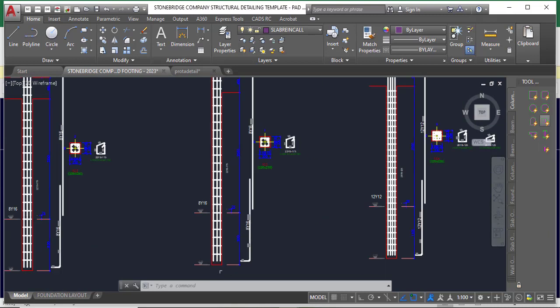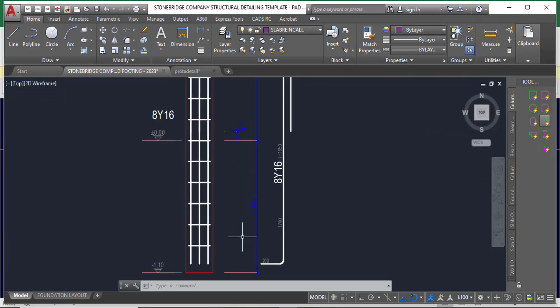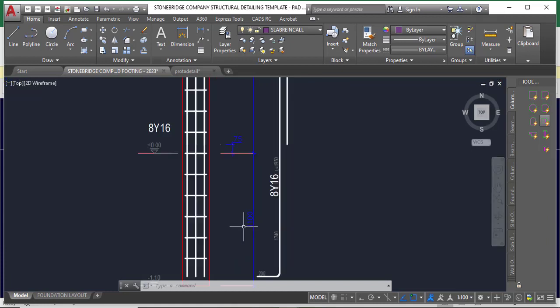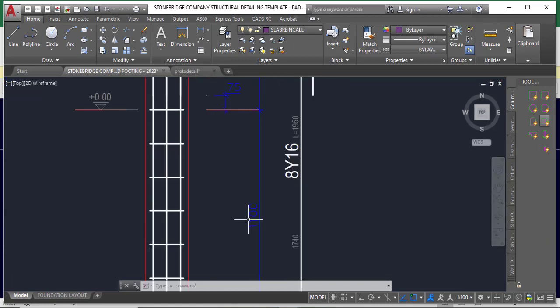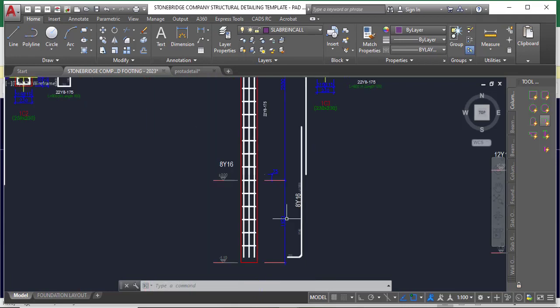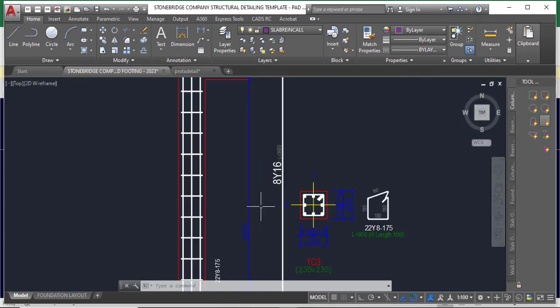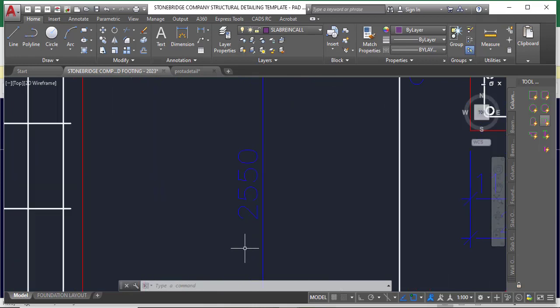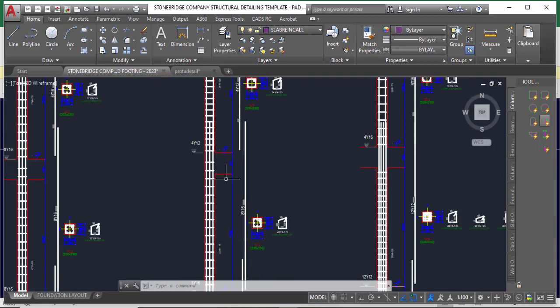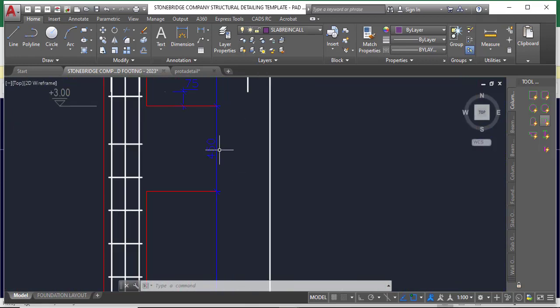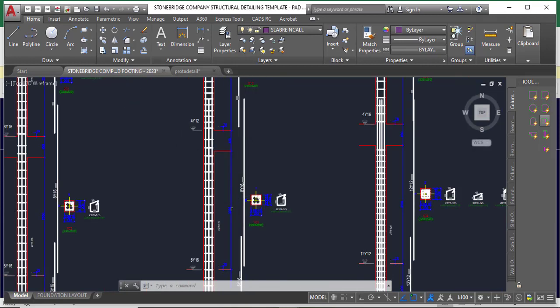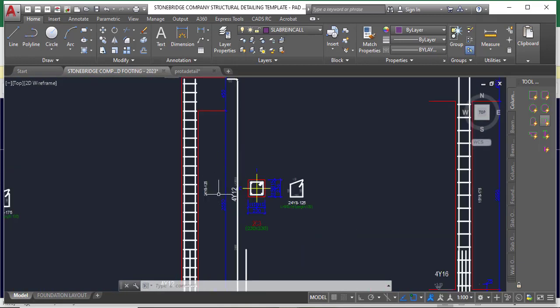So now let's look at this drawing. Looking at this drawing, I have 3 stories. I have the foundation story, I mean the foundation layer. That's the parts for the foundation, which is 1.1 meters. Okay, fine. And then I also have the first floor, which is 2,550 plus my 450 beam, so that gives me 3,000. So the first floor is 3,000, and then the roof floor is also 3,000. So I have 2 floors: the first floor, the roof floor, and I also have the foundation part.